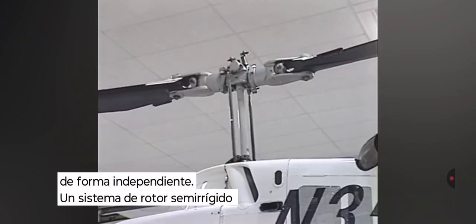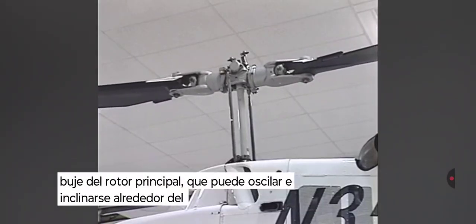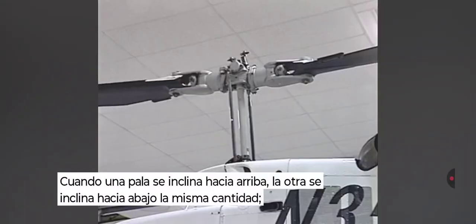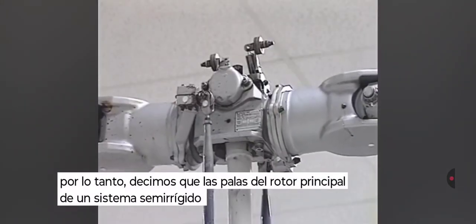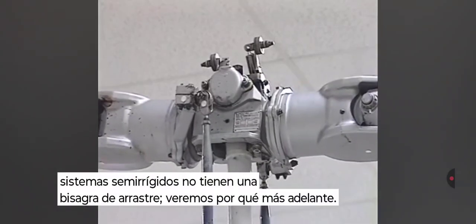A semi-rigid rotor system has two blades. Both blades are rigidly connected to the main rotor hub, which is free to rock and tilt about the rotor mast by way of the teetering hinge. As one blade tilts up, the other blade tilts down an equal amount. Therefore, we say the main rotor blades of a semi-rigid system flap and feather as a unit. Semi-rigid systems don't have a drag hinge. We'll see why a little later.